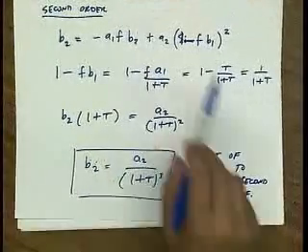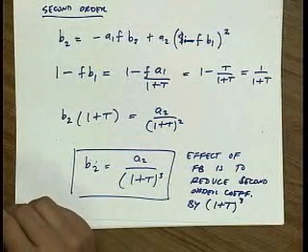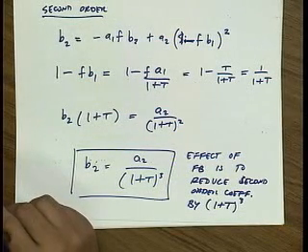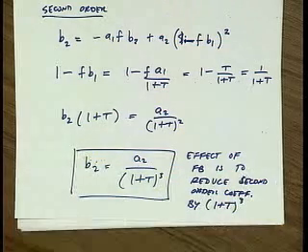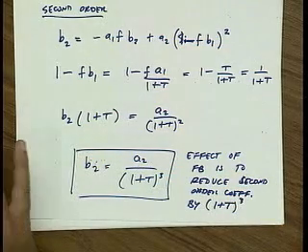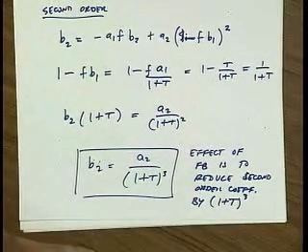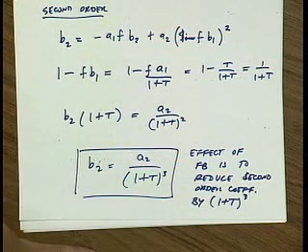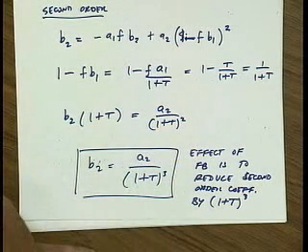I should also mention that we're doing this for a memoryless nonlinear system. Often our feedback network will have frequency dependence. Actually, the forward amplifier may also have some frequency dependence. It turns out, if you're careful, in most cases, if you make T a function of frequency, you still get the right answer. So even if you're looking at a high frequency, as long as you take into account that the loop gain has dropped, you can still substitute here and figure out the effect. Okay.